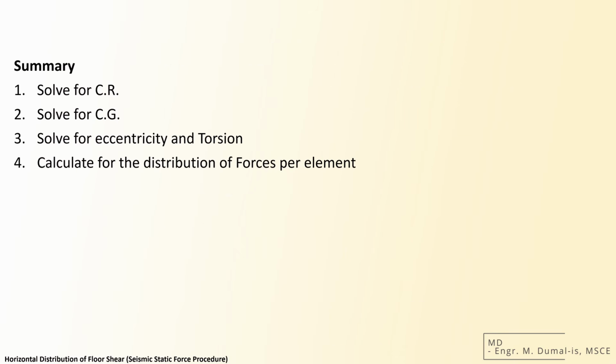In summary, the horizontal distribution of seismic forces hinges on a systematic four-step process. Center of rigidity, CR, center of gravity, CG, eccentricity and torsion, and finally, force distribution. That's it. Thanks for joining me in exploring the intricacies of horizontal force distribution in seismic design.